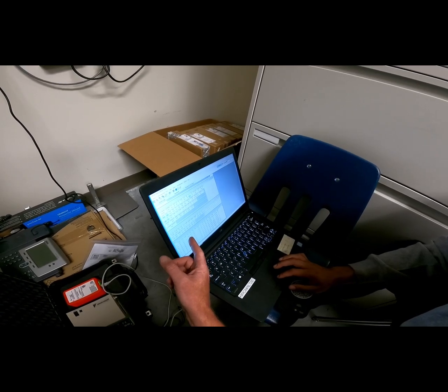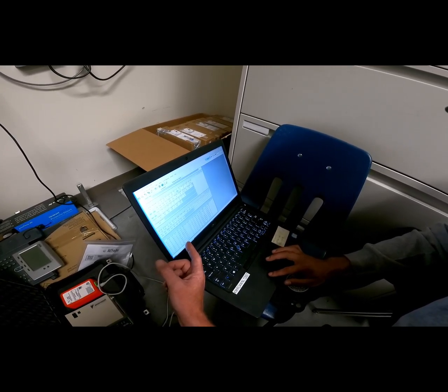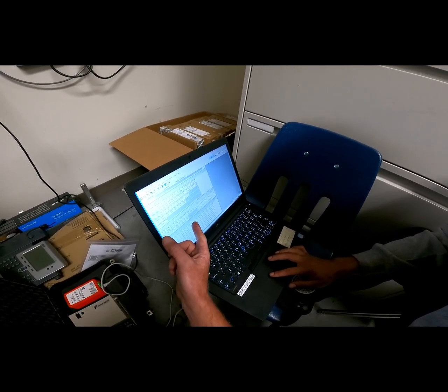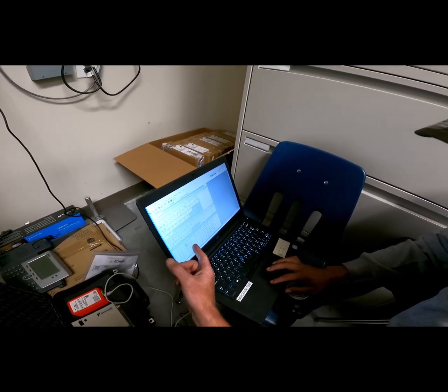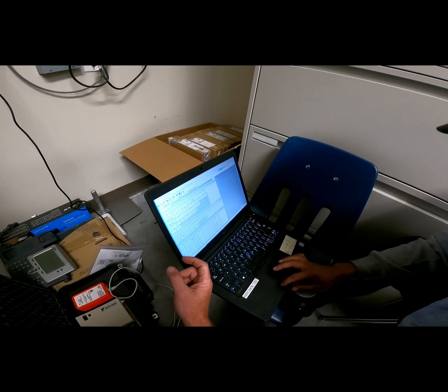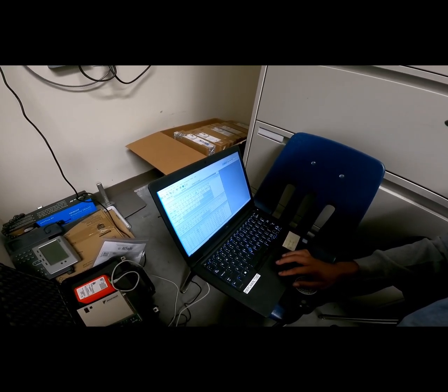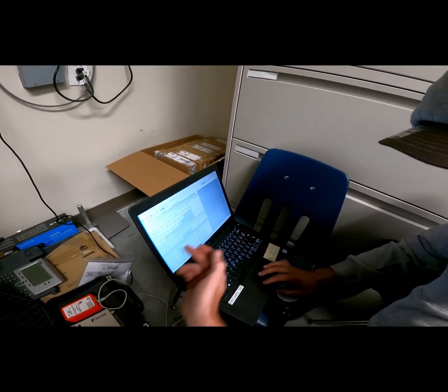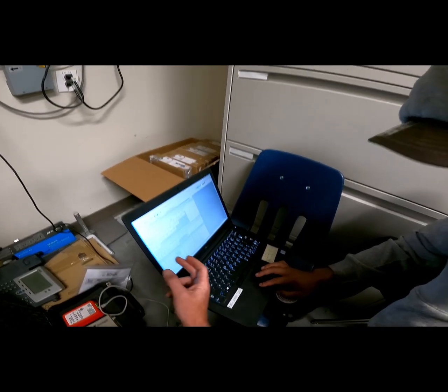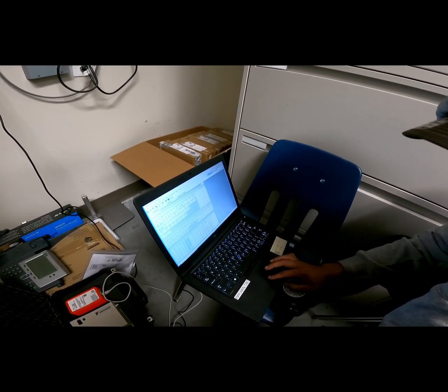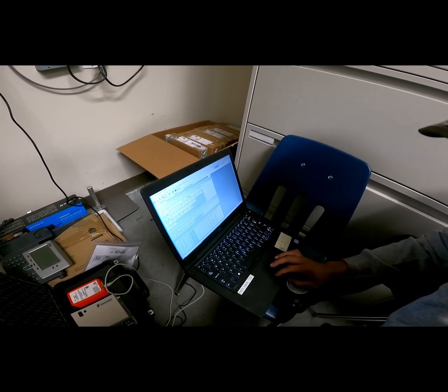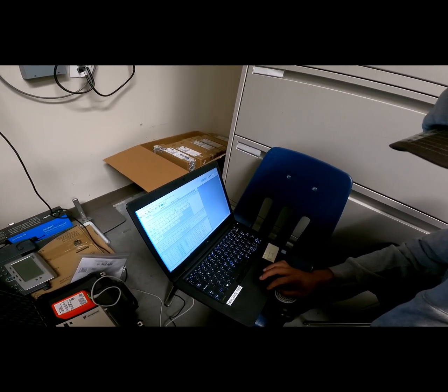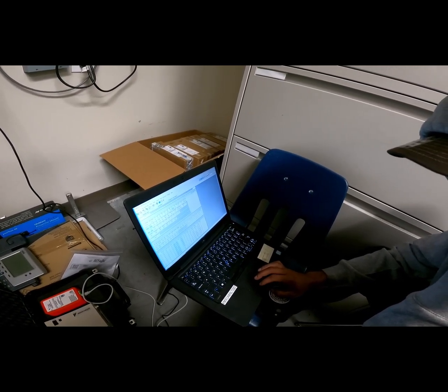These are your return air temps. It's pretty cool in there, isn't it? I want you to highlight all the liquid pipes, all the vapor pipes, and the superheat subcool column. Those are your return air temps, so we don't want those. What we want are the liquid pipes, the vapor pipes, and the superheat subcool. If it's in heating mode, this value will be subcooling. If it's in cooling mode, this value will be superheat. What you want to see is superheat in cooling mode. You want to see superheat values between 0 and 10 degrees.